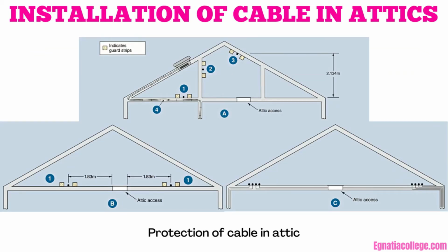The wiring in the attic is to be done in cable and must meet the requirements of Rules 12-500 through 12-526 for non-metallic sheathed cable. These rules describe how the cable is to be protected. In accessible attics, see Figure 16-11A.